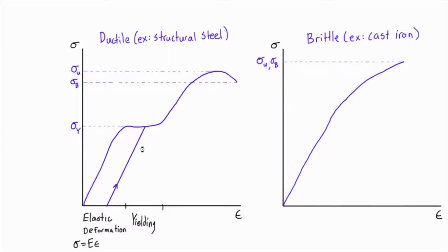tensile loading. Now, if we keep applying even more of the loading in this testing apparatus, and we make it so we have a strain that's actually taking us past this point, and we're into this region now, we get this region and we call it strain hardening. So you can imagine if we loaded it up until maybe here, and then when we go to unload, we take off some of that, we're going to get a profile like this,